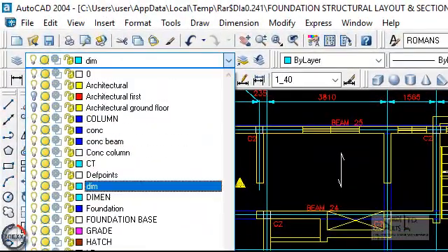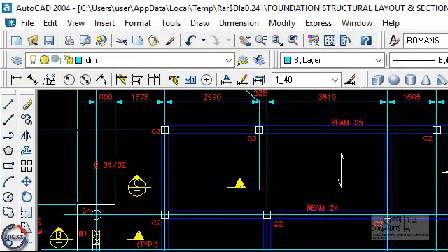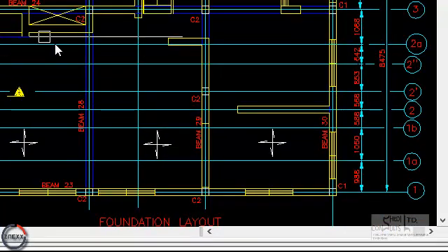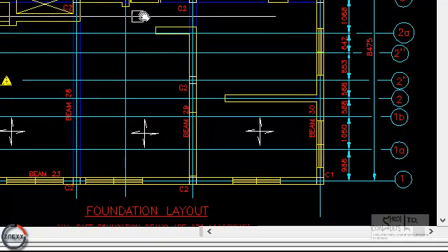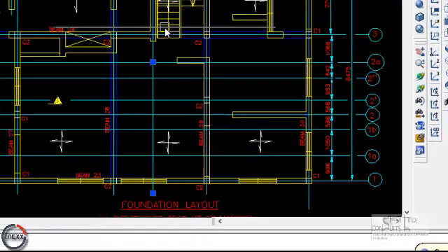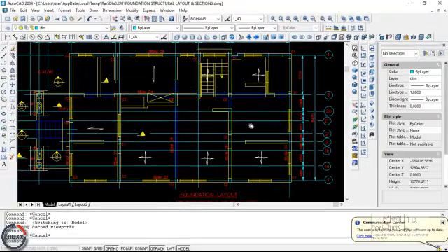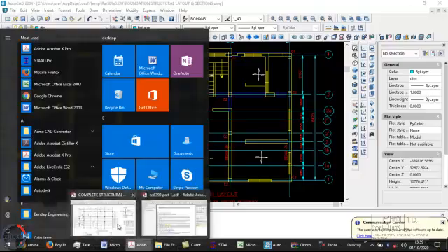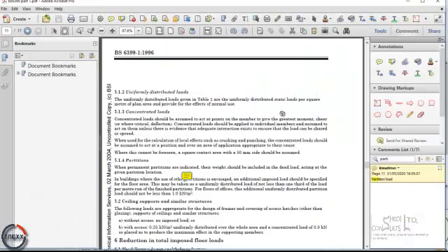So if you look carefully, you would see these are the slab panels for the raft. Now within these raft panels, you're going to have finishes. You're going to have screeding and tiles based on the architectural design requirement. So those finishes, you need to apply the loads associated with those finishes. How do you get the loads? BS 6399 provides a provision.